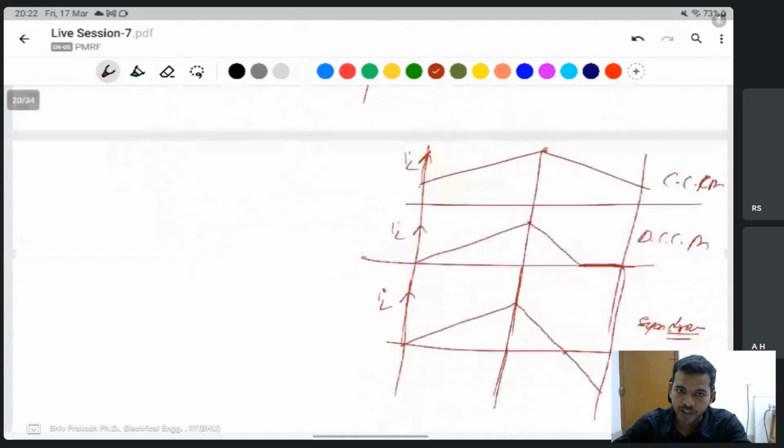To compensate for this, you use the hybrid capacitor. The hybrid capacitor supplies the huge current. So hybrid capacitor, you mean ultra capacitor? Yeah, you supply a huge current in a smaller time. Because the starting current takes very small time, 1 or 2 seconds at maximum. At that time the capacitor will supply the whole current, and the battery will be safe.